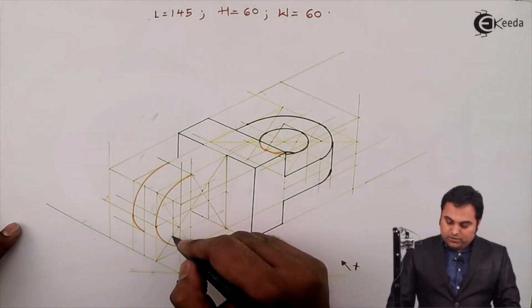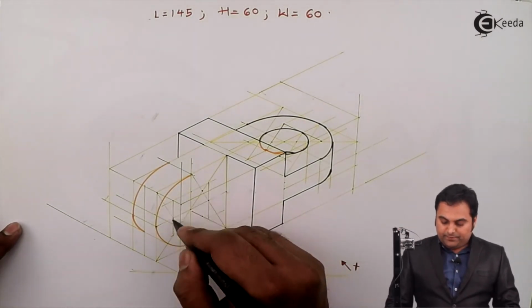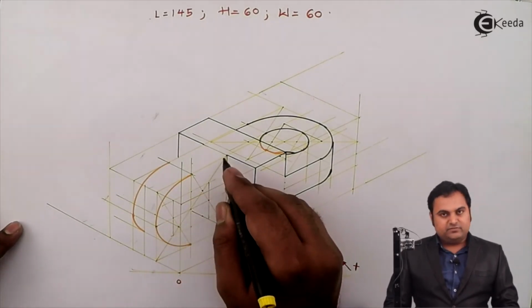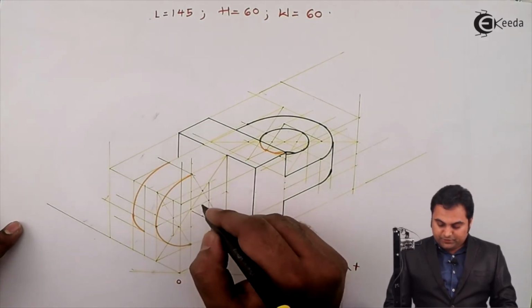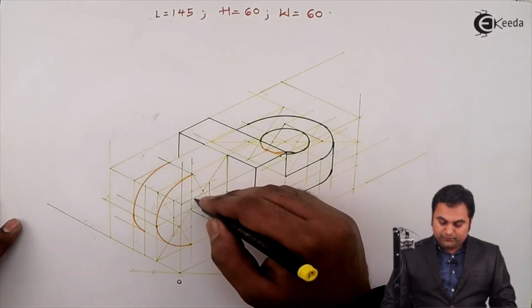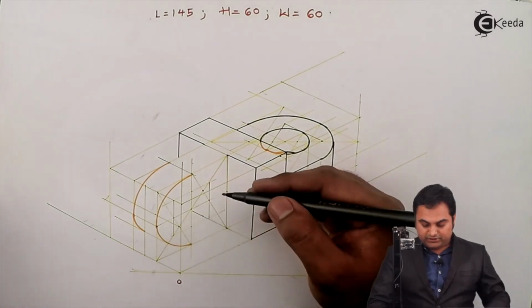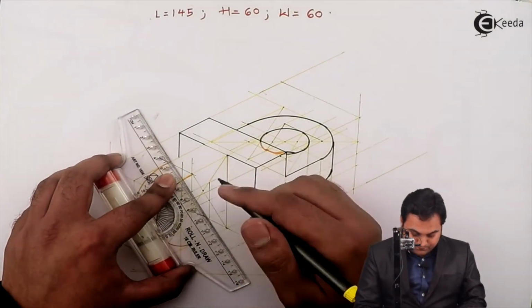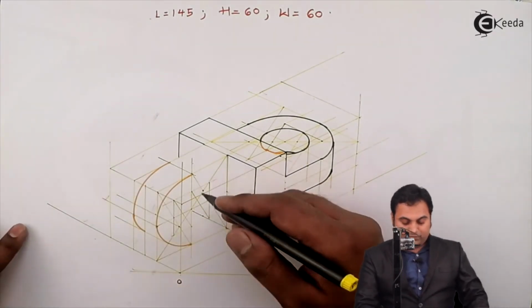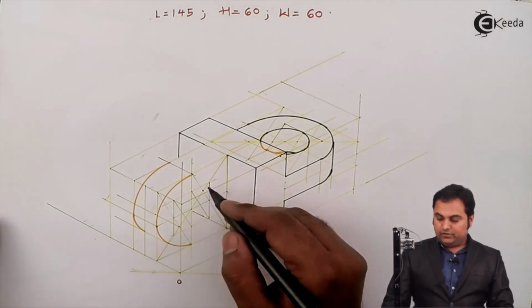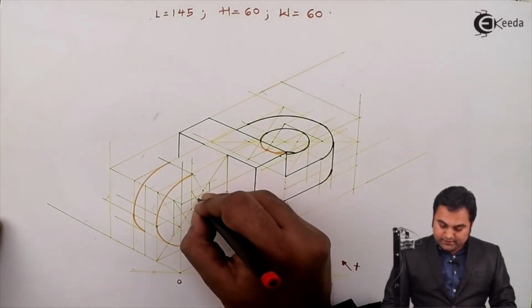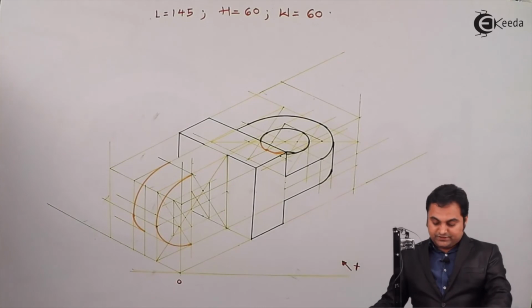And for that, here we have the longer diagonal of the parallelogram for the circle. This diagonal is same as it was for the semicircle. Next, after getting the midpoints, I would be connecting the top midpoint to its opposite bottom corner so that it intersects the longer diagonal, that is joining it in this way. Next, bottom midpoint to the top corner. Now, where these lines are cutting the longer diagonal, those points are nothing but the centers here and even at this location.